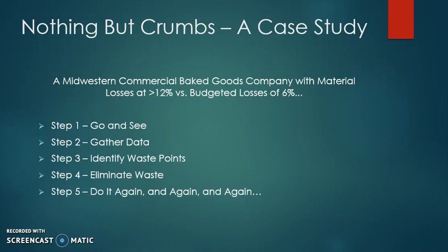And once they've seen the problem and analyzed the data, they need to definitively call out the waste point they're going to go after. Well, let's say in this case they found that the operators were not weighing out the materials with a scale. They were only estimating how much they were throwing in the vat during batching. This lack of adherence to the recipes added up to about 3.5% of the losses the company was incurring. They also saw the material handlers in the warehouse spilling containers and improperly handling returned bags from the line. Now, each of those little spills might not have been much, but adding them all up over the course of the week the management team was out on the floor uncovered another 2.5% material loss.